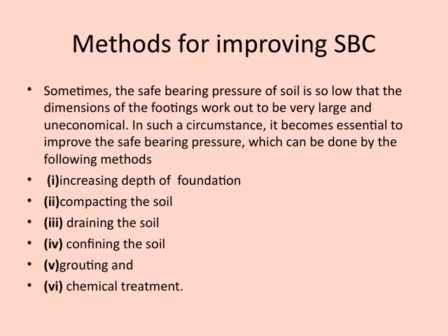Draining the soil helps remove excess water that can weaken the soil's load-bearing capacity. Confining the soil involves applying pressure to reduce its volume and increase stability. Grouting and chemical treatment are also effective techniques. They involve injecting materials into the soil to enhance its strength and stiffness. These methods are essential tools in foundation engineering, helping us optimize the soil's bearing capacity and ensure the safety and